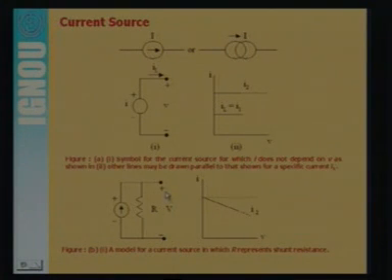That means there is something here where the current is going, which is shown by the internal resistance of the current source. This internal resistance of the current source can be shown only in parallel. Suppose it is delivering a current of 5 ampere. The whole 5 ampere is not reaching the load terminal. Some current, this 0.2 ampere, is passing through the resistance.